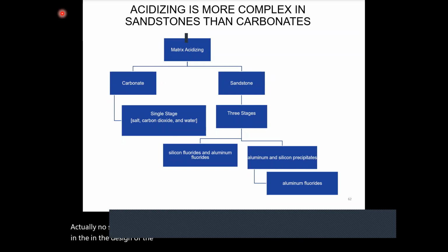Each well has its own characteristics, and that's why I was trying my best to educate the students about going through the manual calculation for the design, such as stoichiometry and kinetics, coming up with the reaction, and calculating the pre-flush, the post-flush, and the main acid,